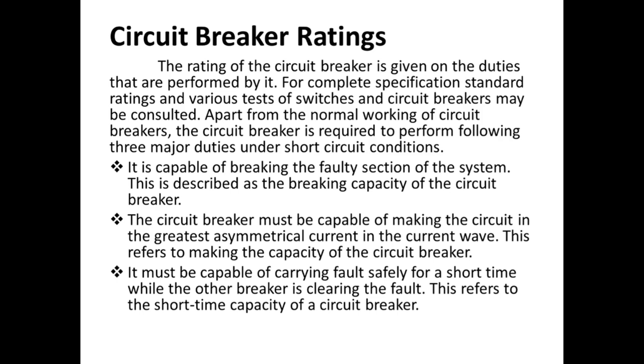Second, the circuit breaker must be capable of making the circuit in the greatest asymmetrical current in the current wave. So this refers to the making capacity of the circuit breaker. Third, it must be capable of carrying fault current safely for a short time while the other breaker is clearing the fault. This refers to the short time capacity of a circuit breaker.